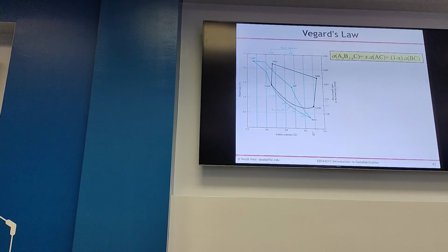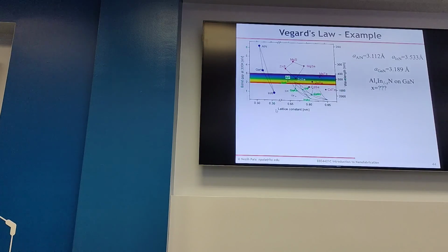Okay, and then you can do the same for nitride-based semiconductors. Again, I probably mentioned that gallium nitride and aluminum nitride, gallium nitride and their compositions, they don't have a substrate. You cannot buy a gallium nitride wafer. You cannot grow it. There are smaller wafers, expensive.